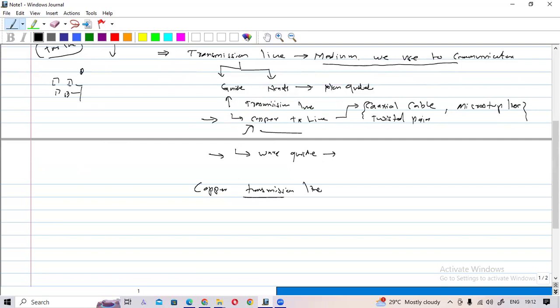If you consider the receiving part, this is connected to a filter, then to an amplifier, a low noise amplifier, then a demodulator. Then we have to decode the signal, then use analog to digital conversion. Then that signal is sent to the speaker.